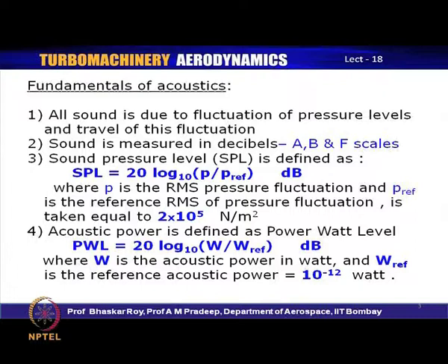Acoustic power is defined as the power watt level, or PWL in some literature, in some books, and this is given as 20 into log 10 W by W ref, and that is also in dB, and W is the acoustic power in watts, and W ref is the reference acoustic power, which is normally given as 10 to the power minus 12 watts.